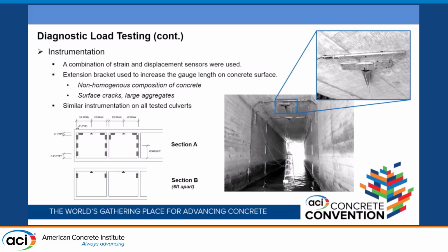As far as the instrumentation details, we used a similar instrumentation plan for all these 10 culverts. We instrumented one exterior cell and one interior cell, and we had two sections instrumented. Section A is heavily instrumented and was intended to capture the direct response from the live load.